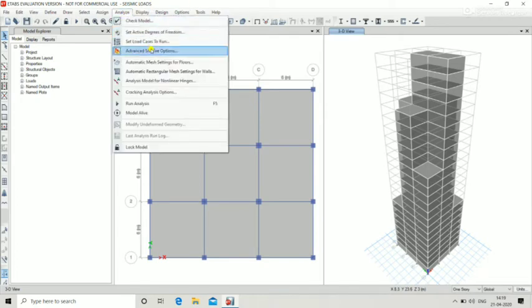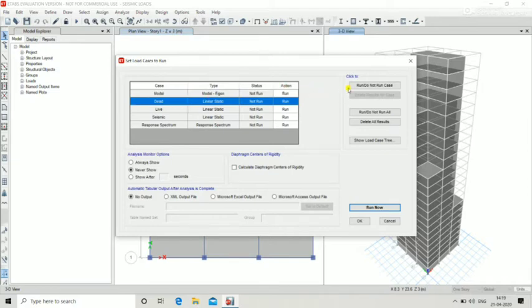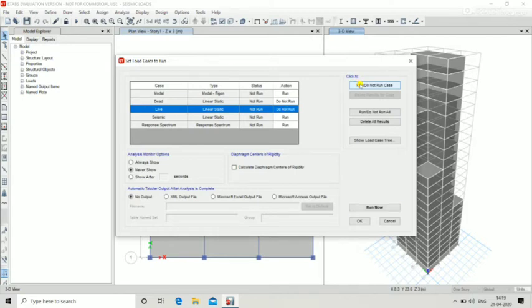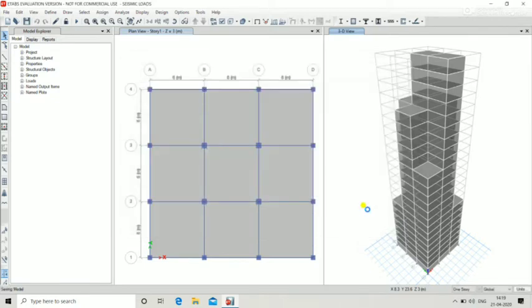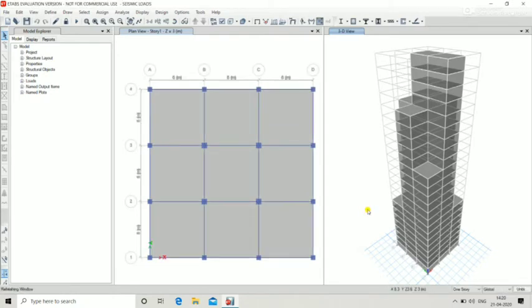For design, click on the design menu, click concrete frame design, and then the start design check option, so that the software starts running the design of the structure. This may take some time. After the design analysis is done, a dialog box may appear showing the concrete frames which do not pass the analysis. So we should click the yes button to continue the design check. Repeat the procedure till the values are shown on the 3D view.